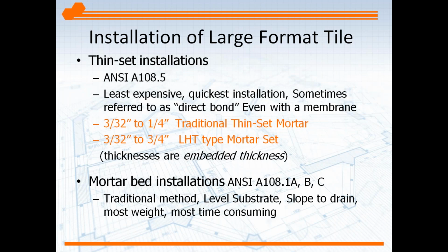So the industry has created, and it's across all the manufacturers, an LHT mortar. That mortar can be installed up to 3/4 of an inch before you push the tile into it. And that allows for the movement of the tile to avoid the lippage and to get the proper bonding on the back of the tile. Embedded thicknesses are above, as I said, 3/4 of an inch, and then you set the tile into it. So the industry needs to use the LHT mortar for large format tile.